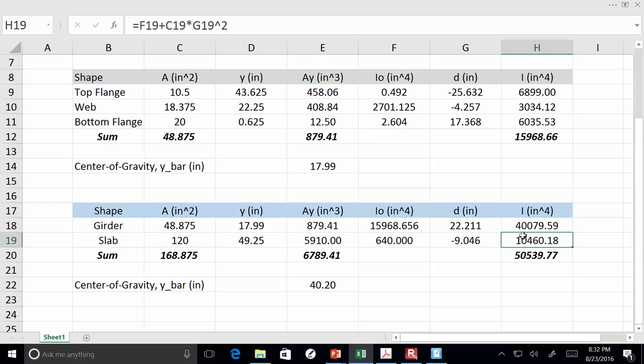All right. That is a short-term interior set of section properties, okay? Now, what if we were doing short-term exterior? What's the only thing that would change? Flange width. What if we were doing long-term interior? Instead of dividing by n, we would divide by 3n, but everything else would be the same, right? Pretty straightforward. This isn't very complicated. And again, the nice thing about doing it like this is that you change a value, everything else changes. Sound good?